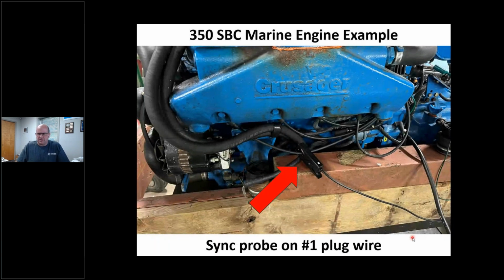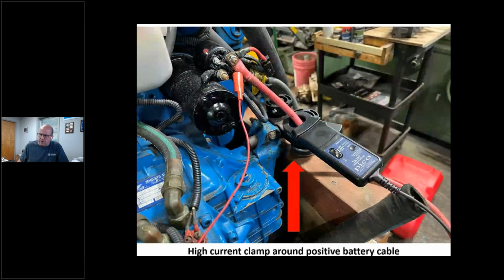I'm ready to do this test. I want to evaluate this Crusader 5.7 out of a Tierra. You see, I've got my inductive spark plug probe on here. I've got my high amp clamp right here. That's the starter, pretty self-explanatory. All right, there's an arrow on my amp clamp.